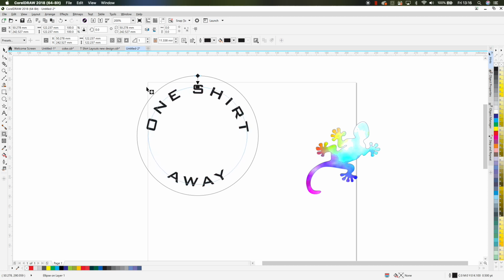And as you can see straight away, the transformation bar at the top there is showing us what size the offset of the contour is, and at the moment that's at 1.4 millimeters, so it's quite small, and we're going to bring that down to about 3 mil. So you can have that as an internal contour. I could have pulled out and it would have made an external contour, like so, outside contour. If I click it, it will automatically do that.